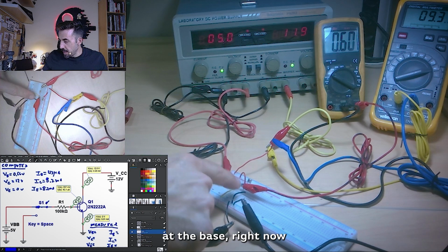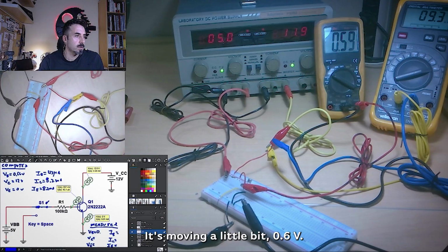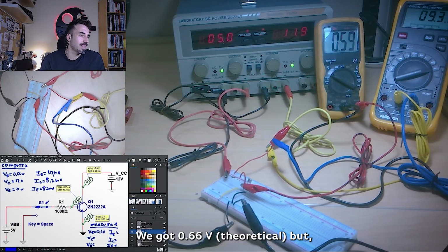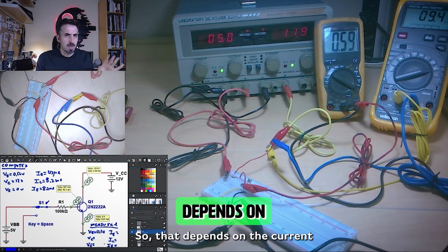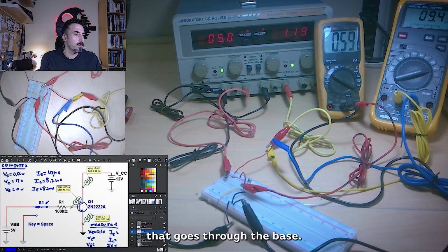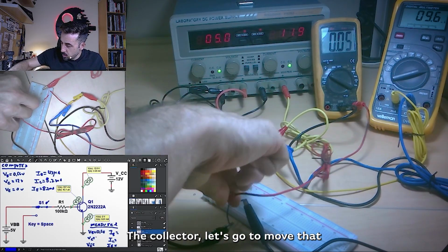So voltage at the base, right now it's 0.6, more or less. It's moving a little bit, 0.6 volt. We got 0.66, but this is a voltage given by the manufacturer, so that depends on the current that goes through the base. The collector, let's go to move that into collector.